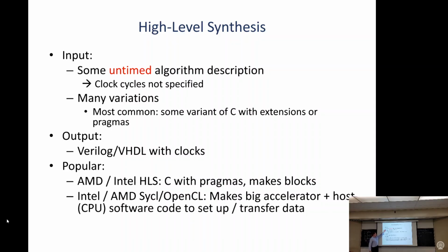But high-level synthesis, again, the key thing that defines high-level synthesis is it's not timed. Okay, so you haven't said what gets done in every single clock. There are a lot of variations. Most of them are some variant of C with either extensions to the syntax or pragmas. Pragmas mean directives to the compiler. So it will still compile in a compiler that doesn't understand the pragmas, but the pragmas give extra information for efficiency, et cetera, to a compiler that knows how to do high-level synthesis. Their output is Verilog or VHDL with clocks inserted.